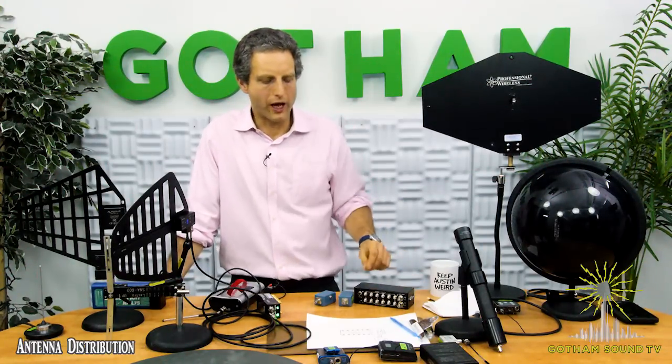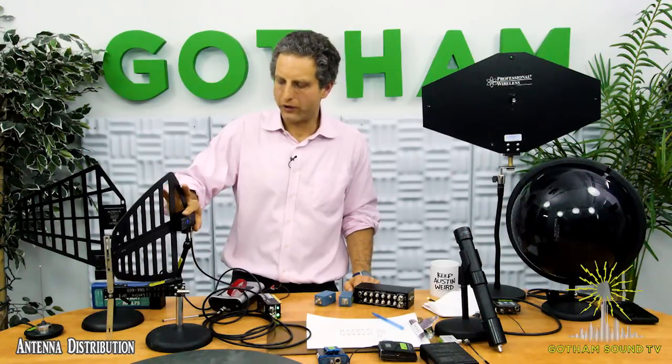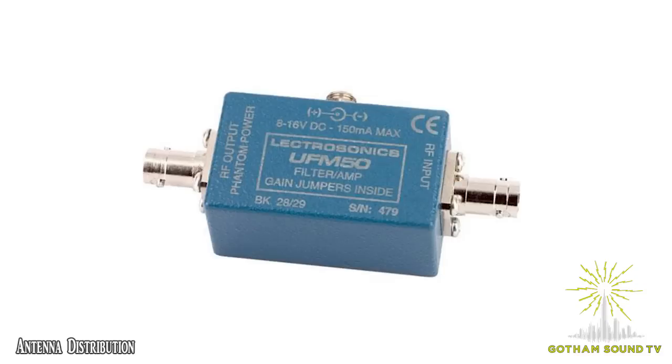And I start to calculate the losses of the cable. We'll put up a link to a table in the text that shows how to calculate the losses for cables. And then that lets me set the gain of my amplifiers. I would put amplifiers like in the animation, either it would be like this kind of amplifier that's connected to the antenna already, or it would be a separate amplifier.